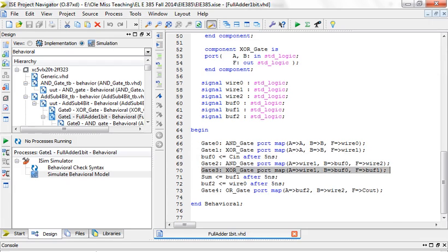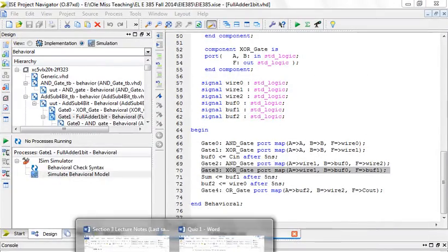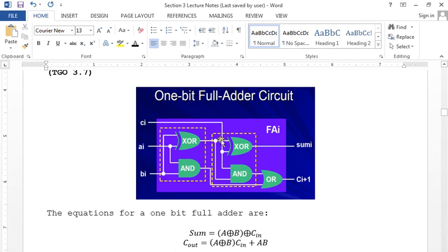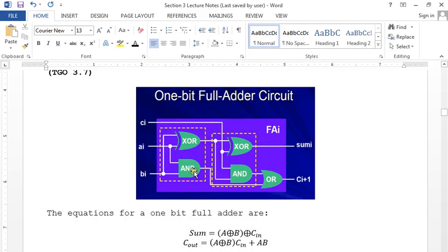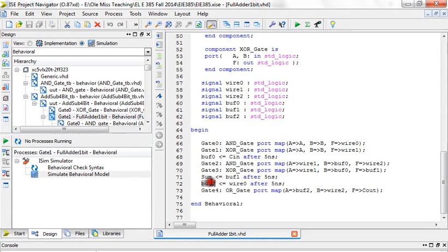And then if you notice, the exact same two signals go into this AND gate, right? So that's why the AND gate matches as well. So the thing is, we want to buffer this signal here, right? Because we don't want it overrunning these two AND gates. So that becomes this buffer.